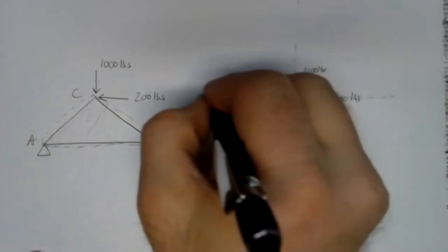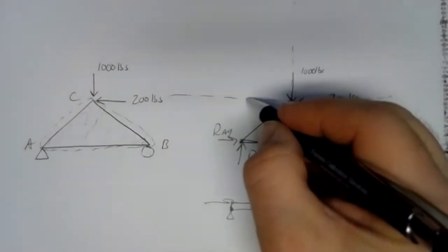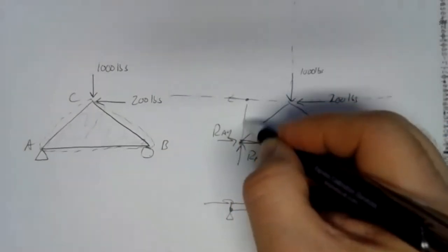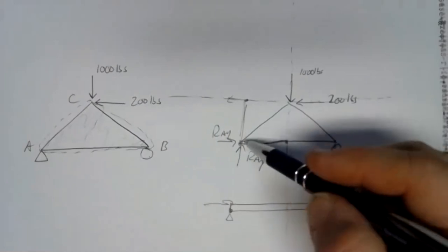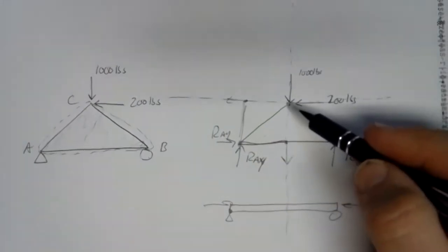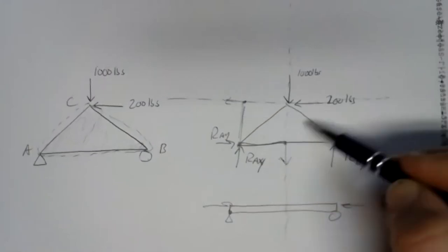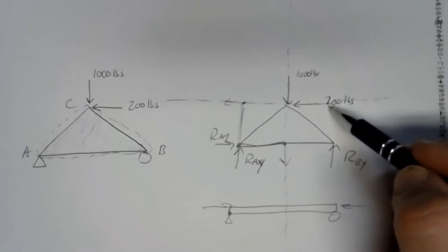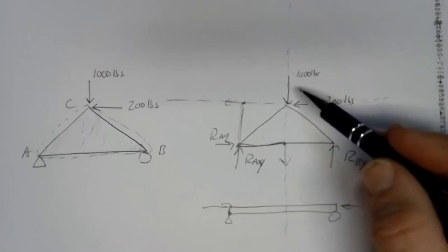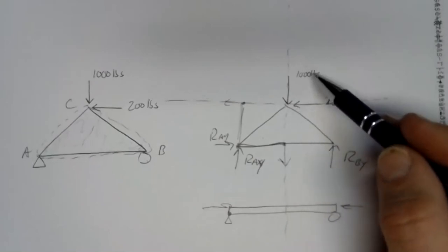If I draw the line of action for that, I shoot this arrow through the air, the closest it ever gets is right there, some distance away from the pivot point, and that distance would be the height of the truss. Figuring out the arms for these forces is not usually hard. It's usually something we can read right off the geometry of the truss. We have to make sure we take them into account, though.